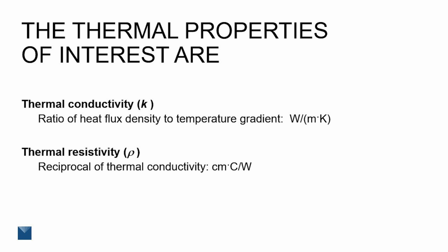So what are the thermal properties that we need to measure? The first two relate to how easily the heat flows through the medium. Thermal conductivity is a measure of the heat flow per unit area per unit temperature gradient. The larger the thermal conductivity, the more heat will flow for a given temperature difference. The thermal resistivity is the reciprocal of the conductivity, and it's used to describe insulation or heat flow in varied